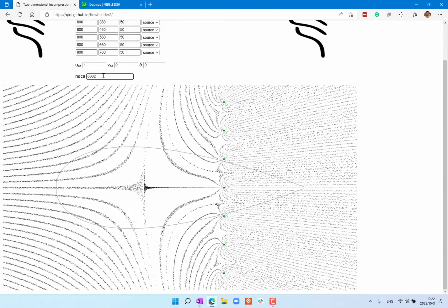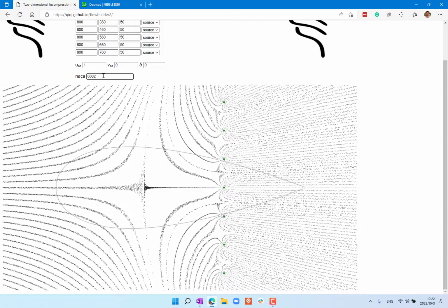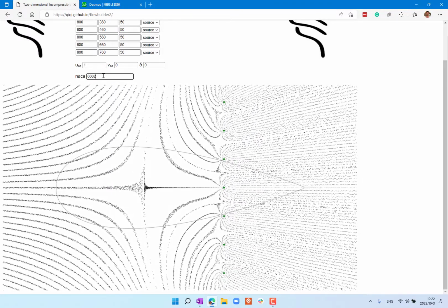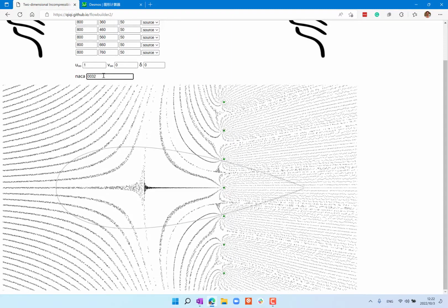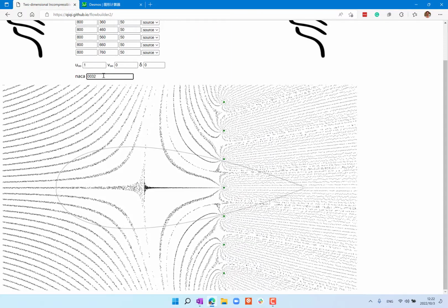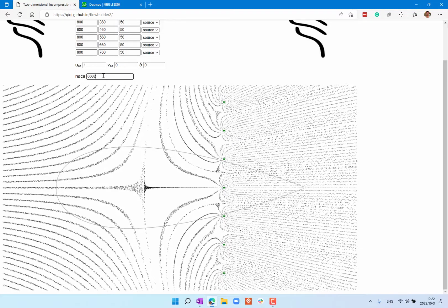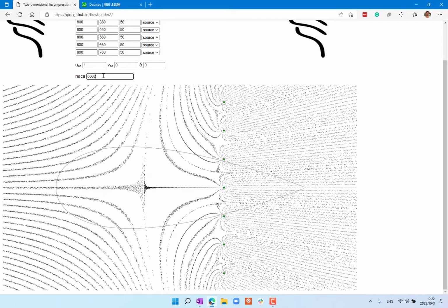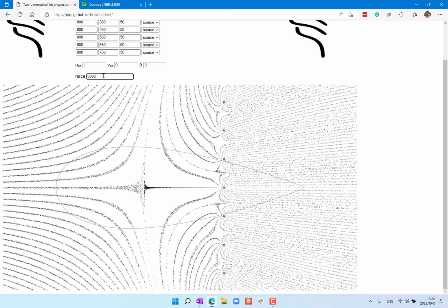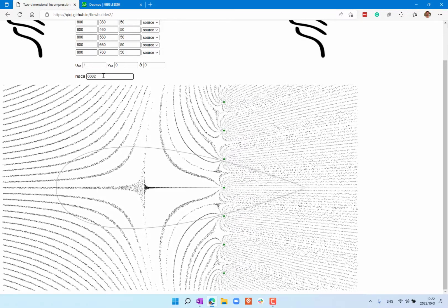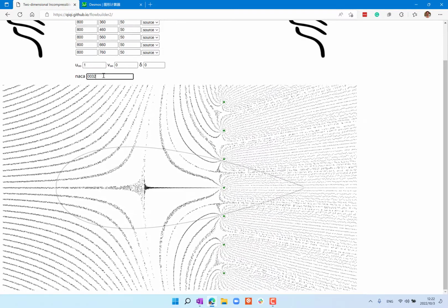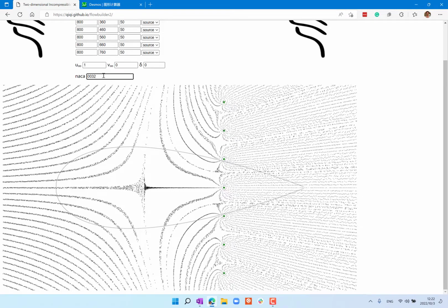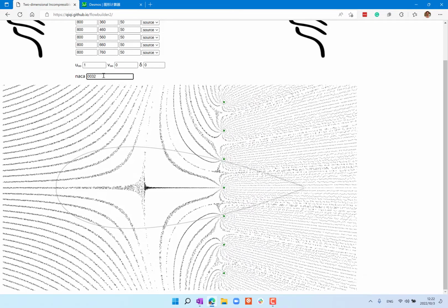So I think in your previous classes you all learned this NACA airfoil designation, right? The first two digits are the camber, basically how the airfoil is non-symmetric, and the later two digits are the thickness to chord ratio. So 32 means the thickness is 32% of the chord length. If the structure is more important than aerodynamics, but you still want some aerodynamic consideration, something like this is a perfectly valid design on the airplane. All right, because it is thick enough for bending moments and things like that, but still reasonably aerodynamic.